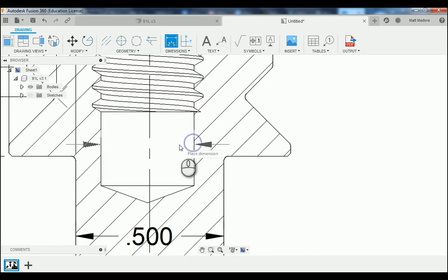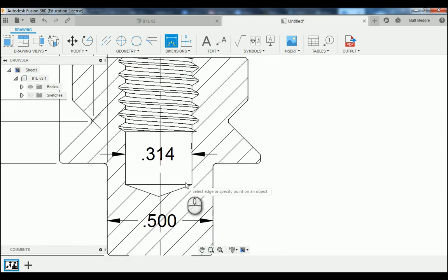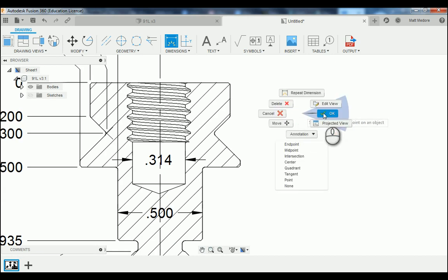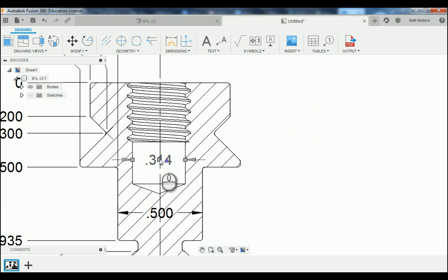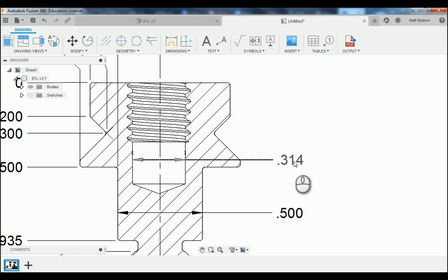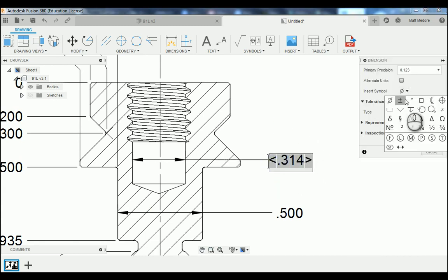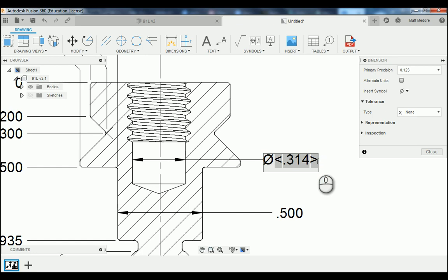We're going to double left click on these, insert the diameter symbol, and then type in this information. That's the wrong symbol. This hole needs to be drilled 600 thousandths max, and you are going to be using a 140-degree included angle drill bit. We'll close that out.